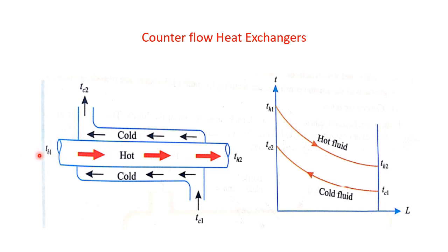You can see here the hot fluid is moving from left to right, whereas the cold fluid is moving from right to left in the heat exchanger. For that purpose, it is called the counterflow heat exchanger. In the counterflow heat exchanger, both hot fluid and cold fluid flow simultaneously and parallel to each other, but the directions of the hot fluid and the cold fluid are opposite to each other.